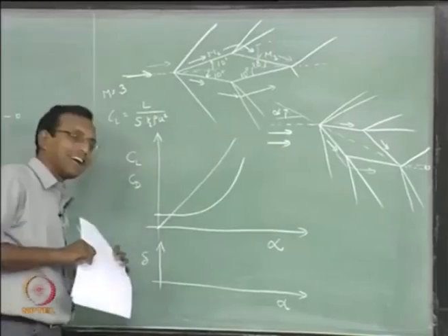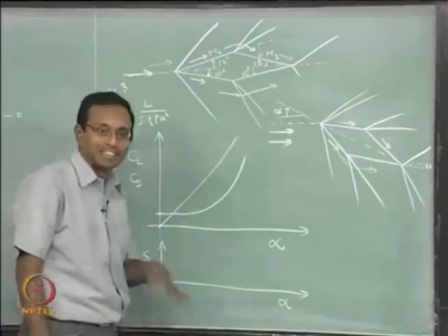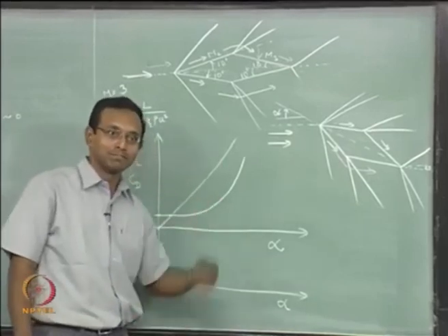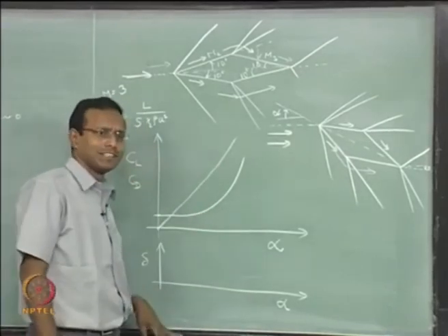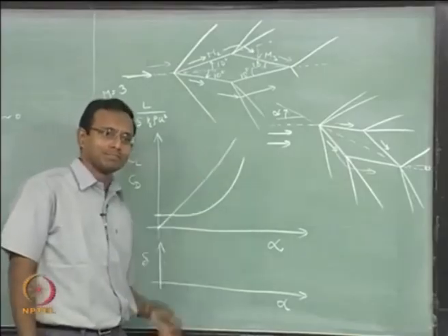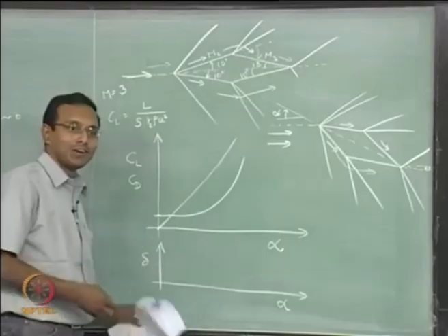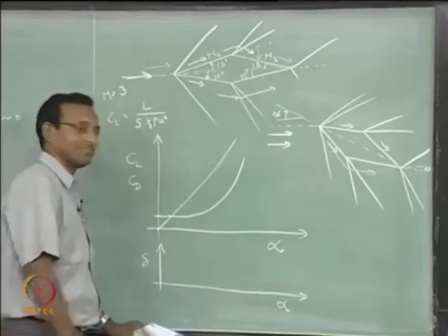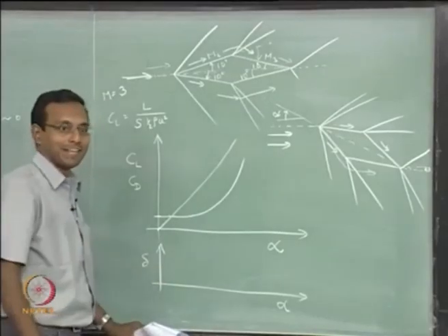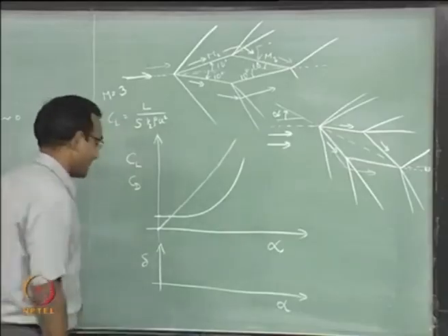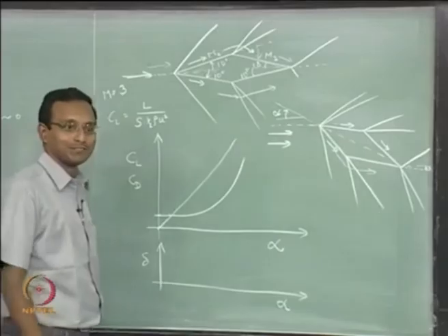Okay. The way I think about downwash is like you are climbing stairs. What do you do? You kick that particular stair down so that your body goes up. That is what the airfoil is doing. It is kicking the air down so that it goes up. That is lift. This is the way you think about it when you talk Newton's laws. Same Newton's law working here. The airfoil is kicking the air down so that it goes up. Okay. That is action and reaction if you want to think about it.